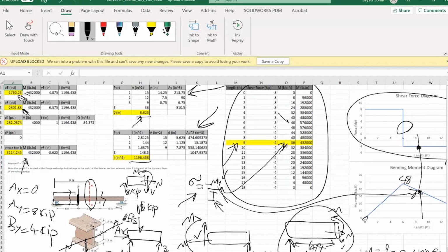You see, you're going this way from the neutral axis to the bottom. So that's equal because we measured the position of the centroid from the very bottom layer. Then as a result, the value for it would be this. So that's what you see over here. And overall, we get a positive stress of the magnitude that you see over here, 3,000-something psi. Okay, so this is as far as the bending stresses.